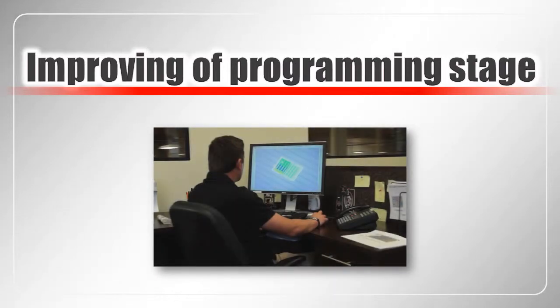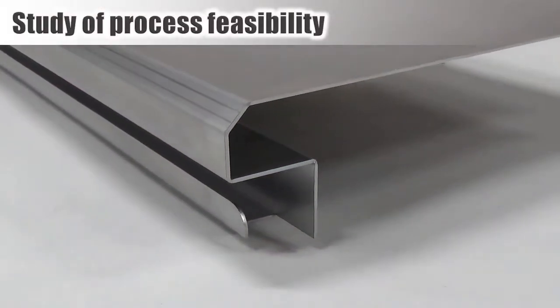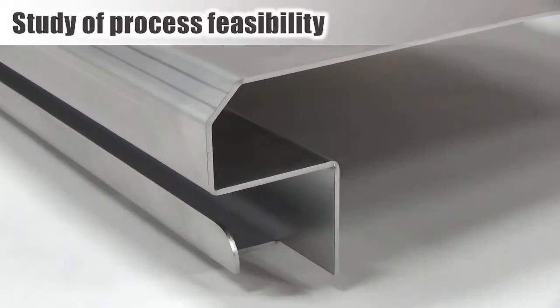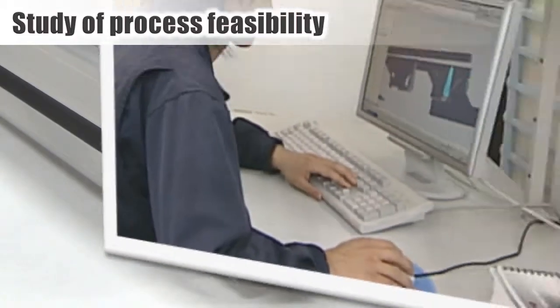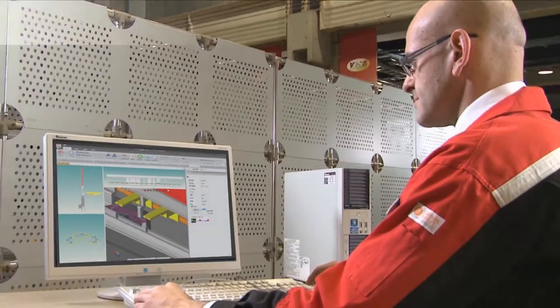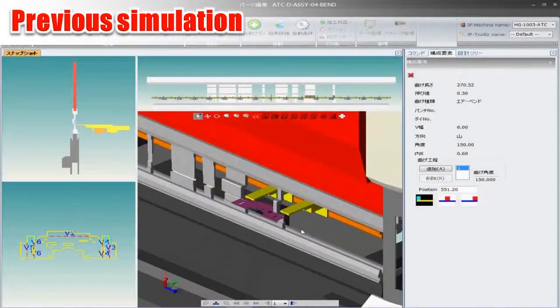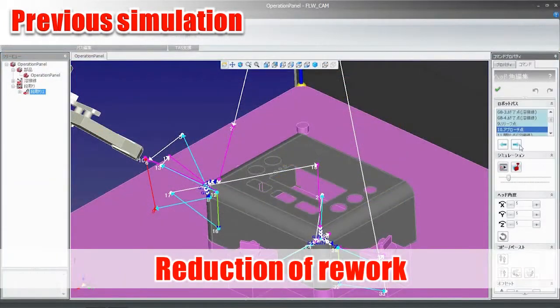Lastly, we would like to propose efficient programming. For complex shapes like these, time is spent with the study of bend sequence, tool selection, and welding feasibility in the programming stage. By utilizing simulation, feasibility checks are done easily in short time, eliminating reworks at the shop floor.